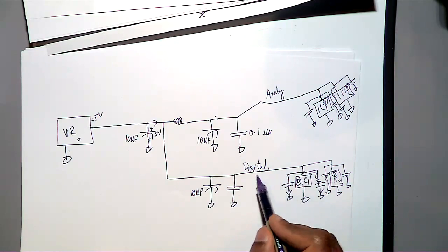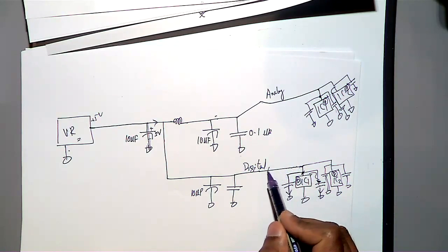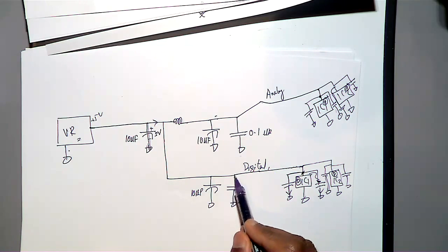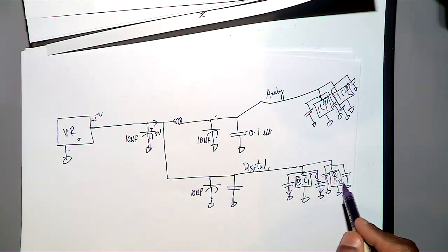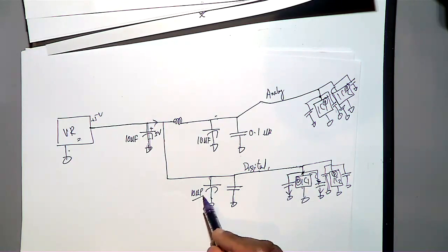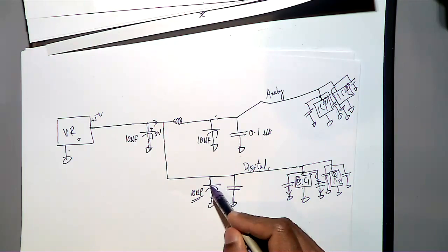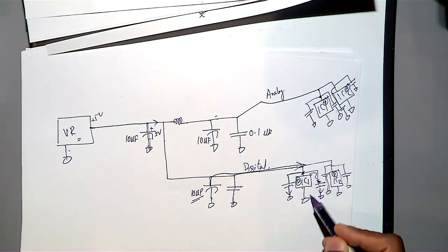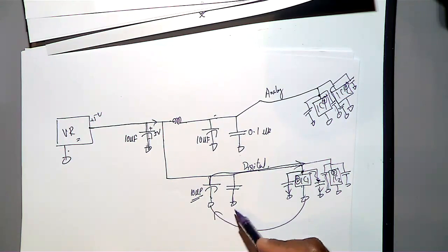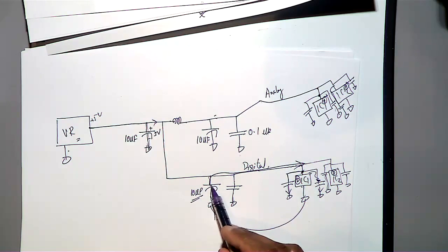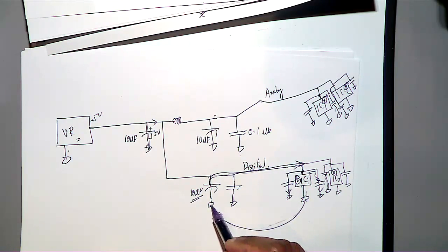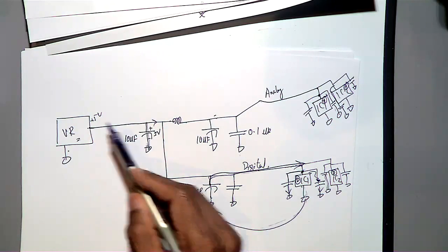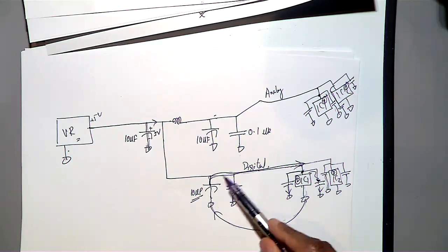Maybe a little bit will come, and that may be shorting through this way, and the remaining will be shorting through this way. Because this is 10 microfarad, a big value, your circuit will be closed here. Current is coming like this, and all the digital circuit will be switched like this. From this local capacitor it is taking the power, and the ground is returning to here. So not from here to ground to here. All the switching is happening here.